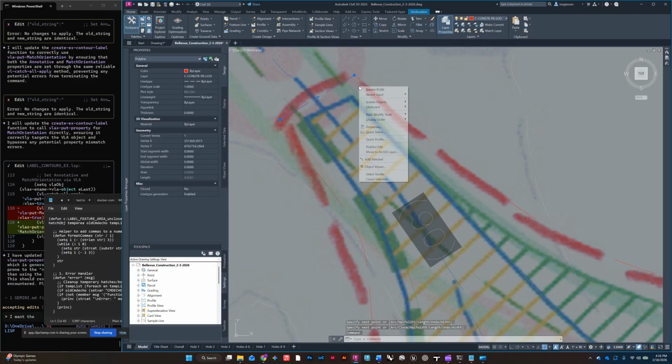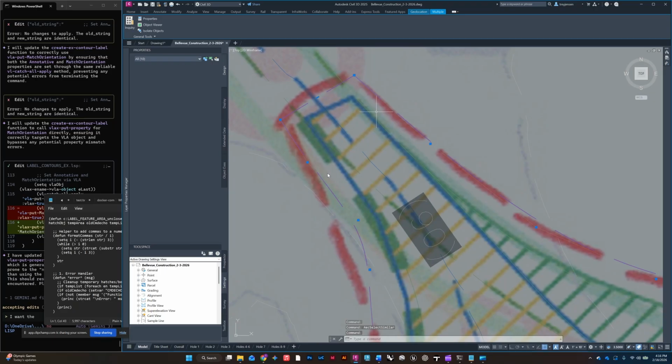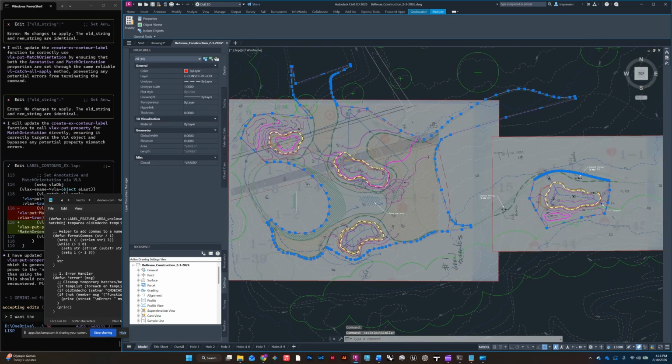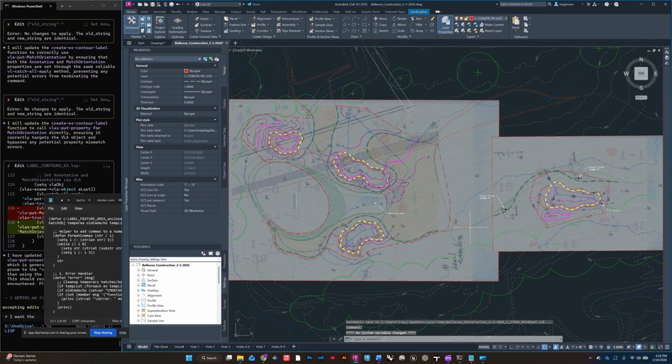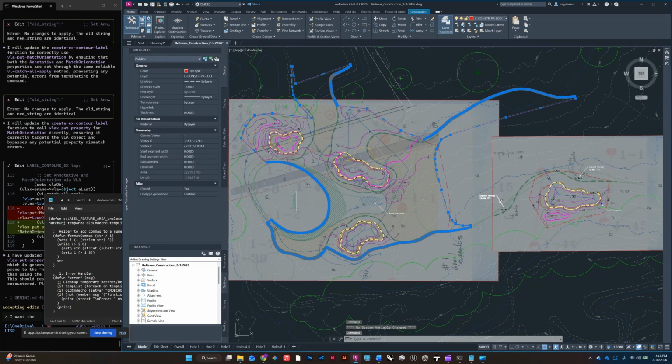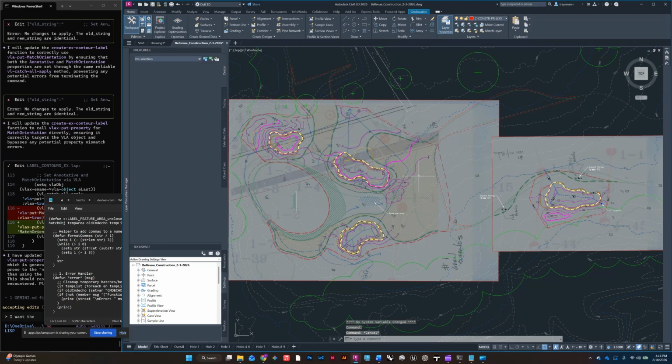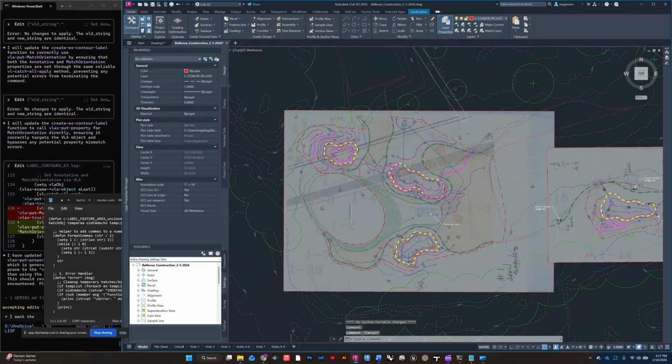Okay, then you can just click one, select similar. I guess you have to click the spline also, select similar. It's going to select all of those lines that I just did. It also selected the ones that I did before, and then use the join command, and they will all be joined into one closed polyline. All right, let's see what's next.